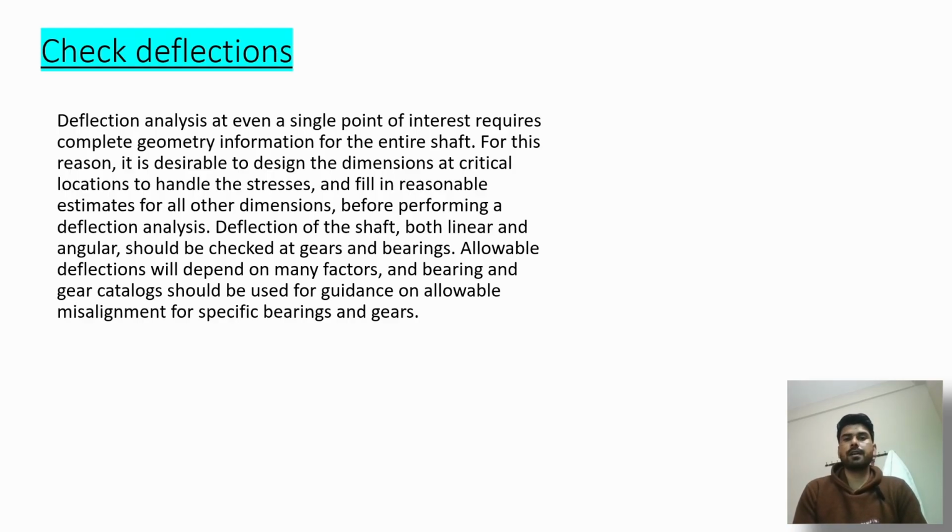Before performing a deflection analysis, deflection of the shaft, both linear and angular, should be checked at gears and bearings. Allowable deflections will depend on many factors, and bearing and gear catalogs should be used for guidance on available misalignment for specific bearings and gears.